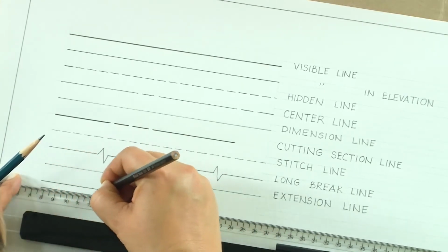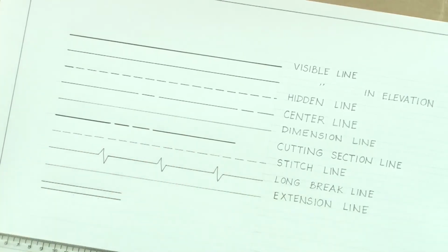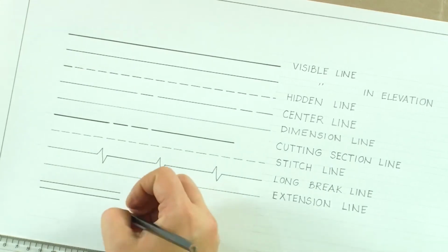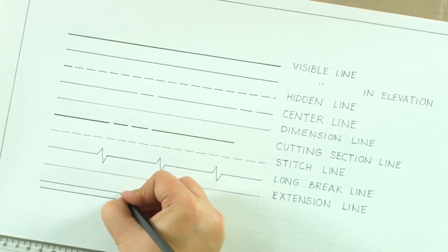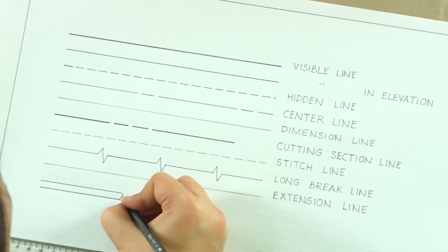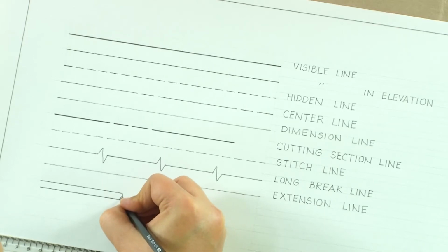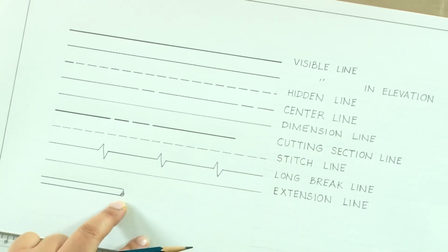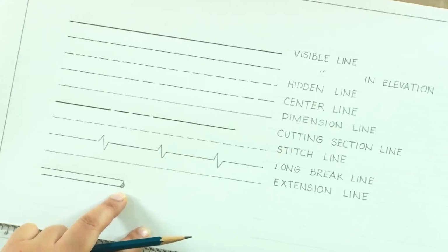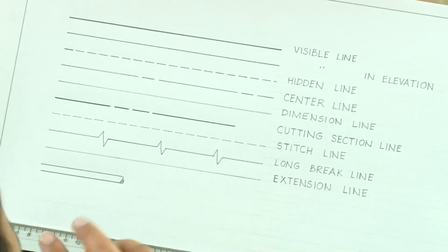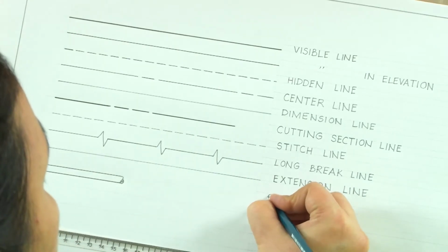So, just imagine that this is a pipe which is going to be cut, and at the cut end, we will draw a curved part like this, and it is then hashed. This is the standard for showing a break line for the curve. So, we can write it as the curve break line.